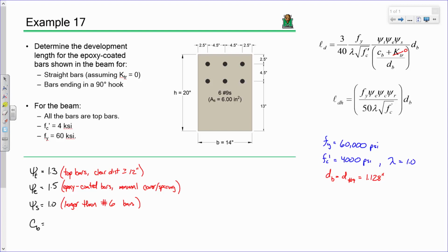2.25. Does everybody see that? Remember, for any one bar, we take the minimum of 3 distances: how far it is to here, how far it is to here, and how far it is there. And it's that center spacing that's the worst, or the smallest. From there to there is half that, so that's 2 1/4. That's the same distance, actually, for all of the bars here, okay?